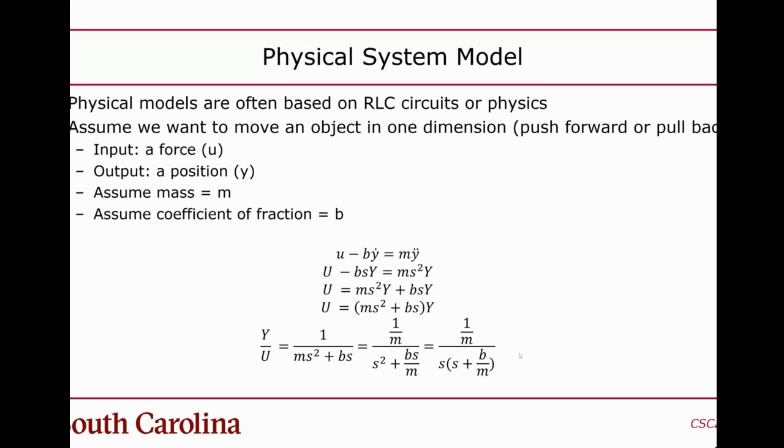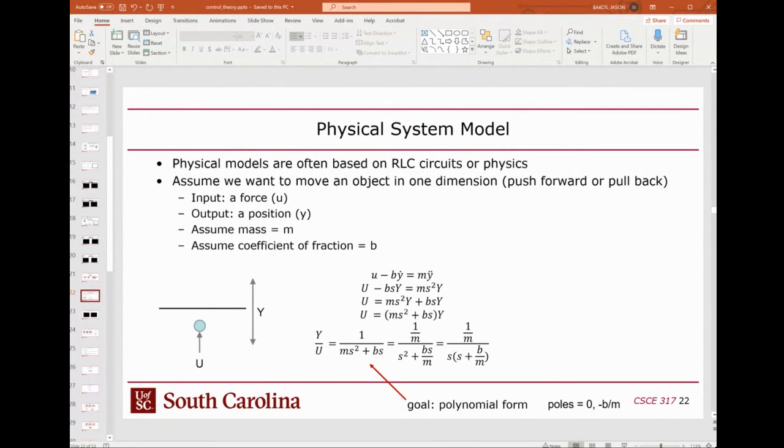And so in order to stabilize it, we would have to multiply it against a controller transfer function to get an open loop transfer function. And then optionally, we can also do a closed loop transfer function as well to make a more robust controller.